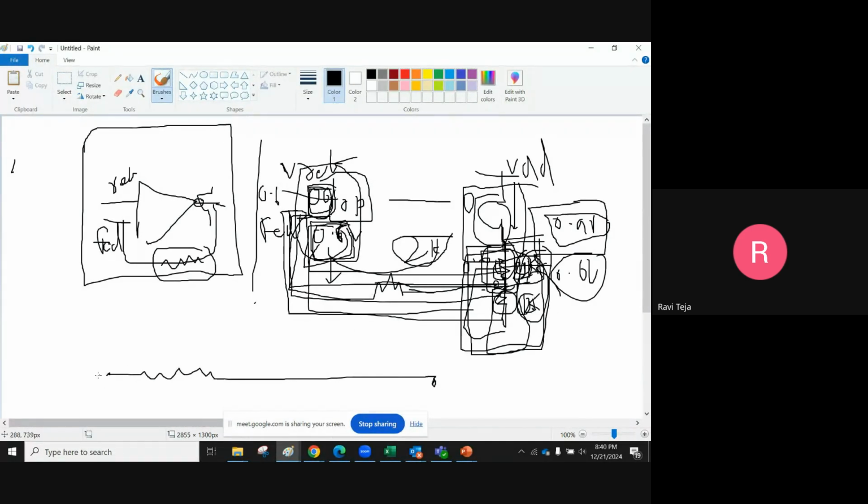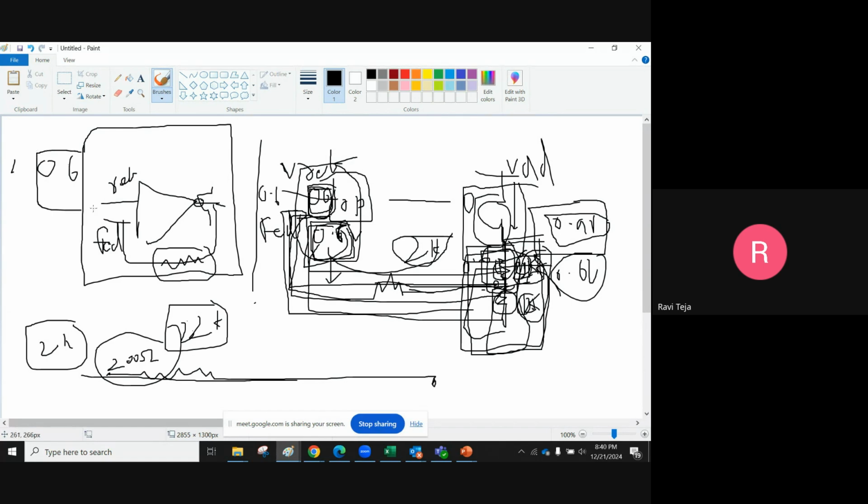But as you add this routing resistance, instead of 2k, if you are adding some 200 ohms of routing resistance, it becomes 2.2k, right? If it is 2.2k, then the feedback can never be 0.6 volts. That means this regulator will never work.